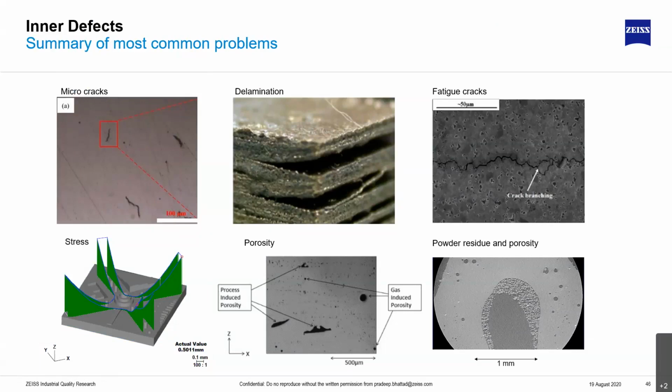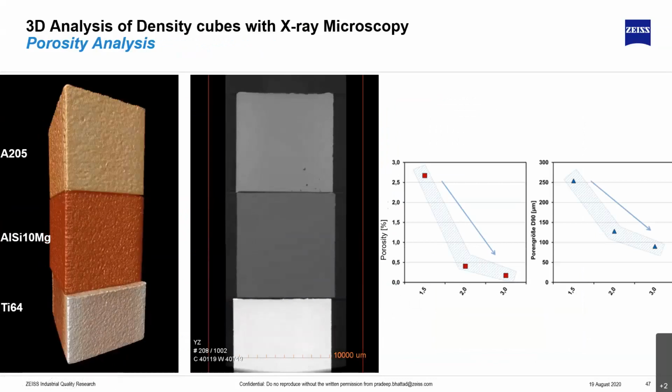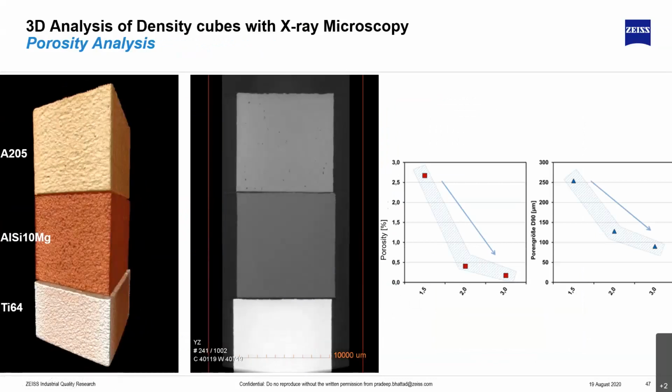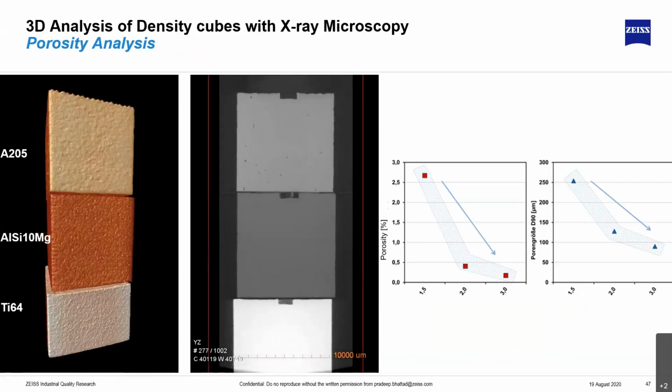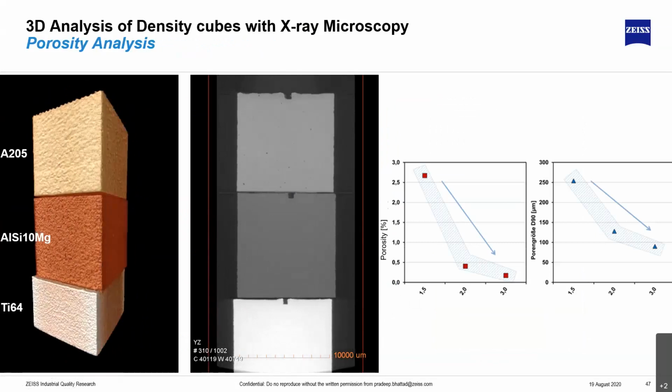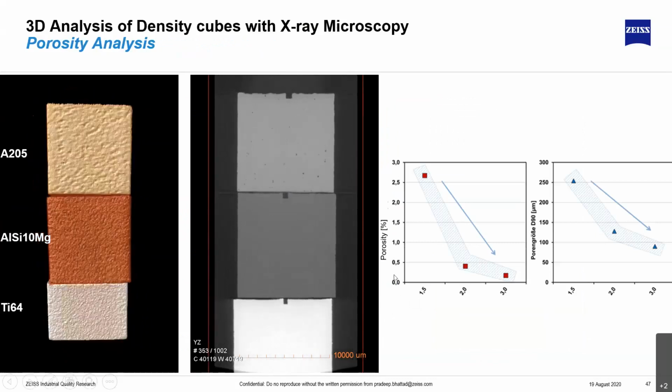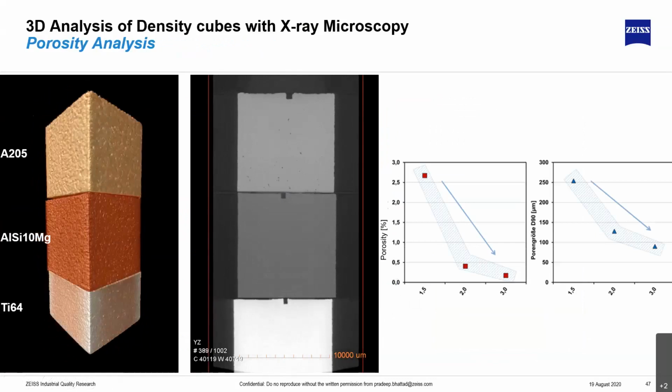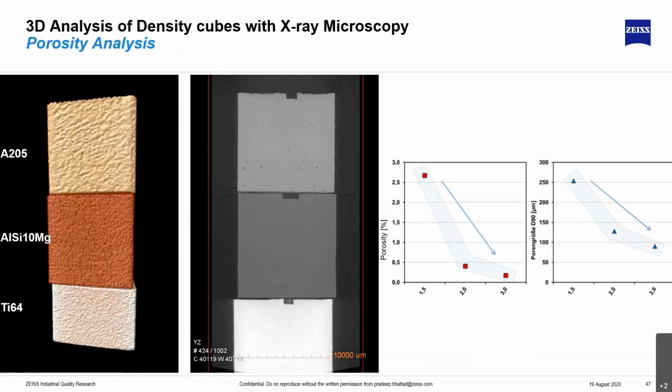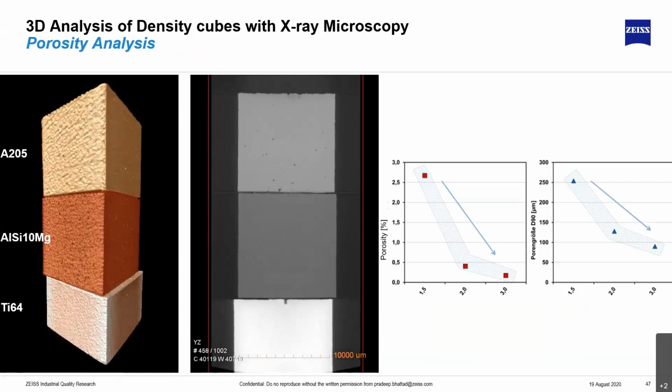So what we typically look for when it comes to defects is, of course, the porosity, delamination, and depowdering. So I'll focus on just a couple of those things. Based on your answers, I can see almost everybody prints coupons with their builds. So one of the things that everybody does is, of course, Archimedes density, but at the same time, optical cross-sectioning. Take cross-section and measure it under optical microscope. So these are the two steps that are taken with each other.